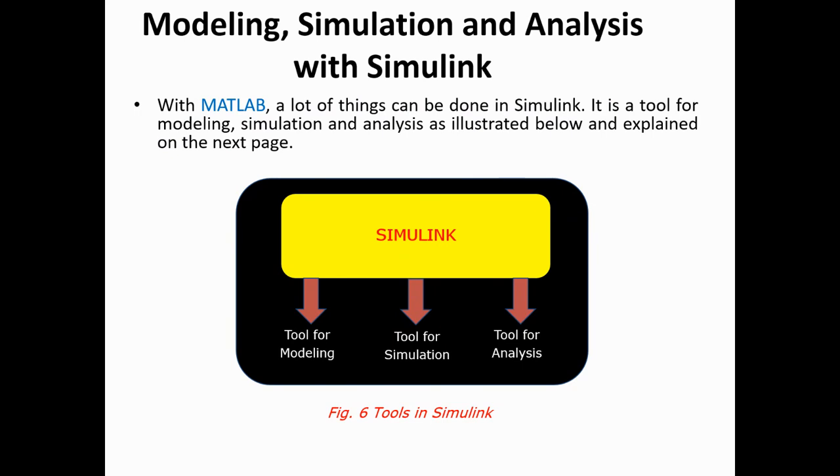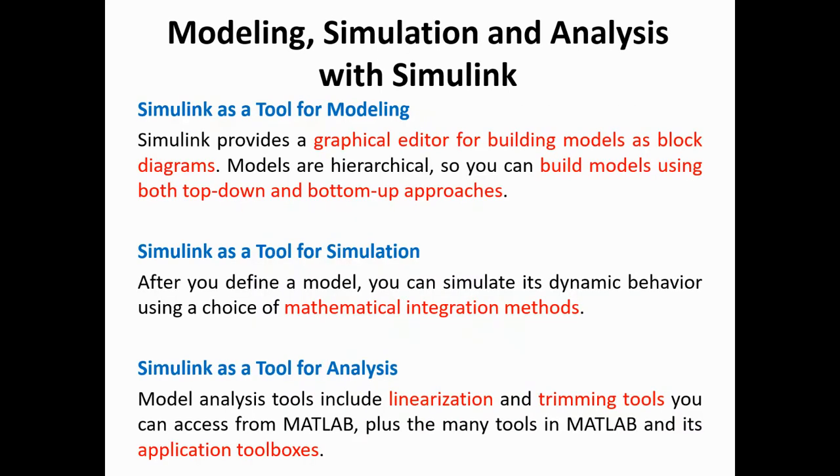It is a tool for modeling, simulation, and analysis as illustrated below. So you have a lot of applications that you can use for your Simulink model. It is a tool for modeling because it provides a graphical editor so that you can build models as block diagrams. So it's just making a diagram from the interface so you can make models out of it. You can do the bottom-up approach or the top-down design. When you speak of top-down design, you start with the specification itself before building the circuit. But when you do the bottom-up approach, I'll give you the circuit and you do the specification.